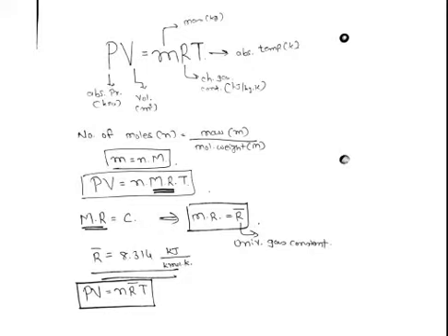The universal gas constant has a particular value, 8.314 kilojoule per kilomole Kelvin, and so we can modify this equation as Pv is equal to n R bar T. And the value of the characteristic gas constant, kilojoule per kg Kelvin, is 0.287 kilojoule per kg Kelvin. So remember that value, and this is a really important topic, so remember this formula.